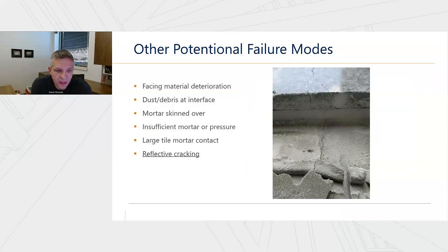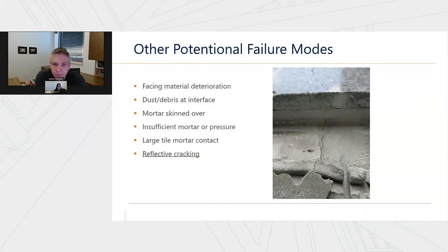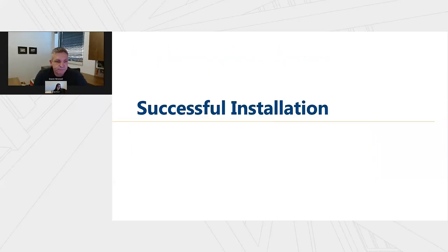And then reflective cracking. If you've got the facing material bonded directly to the backup, then there's the potential that if the backup's an unstable material, the cracking that occurs at the backup can reflect to the surface. And with that, I'll hand it over to Renae to talk about successful installations.